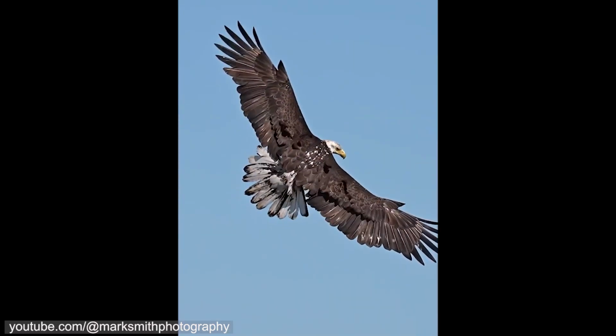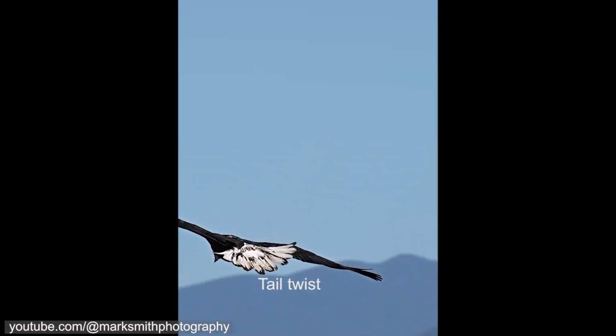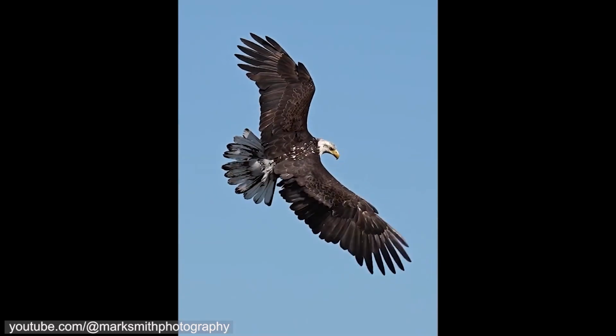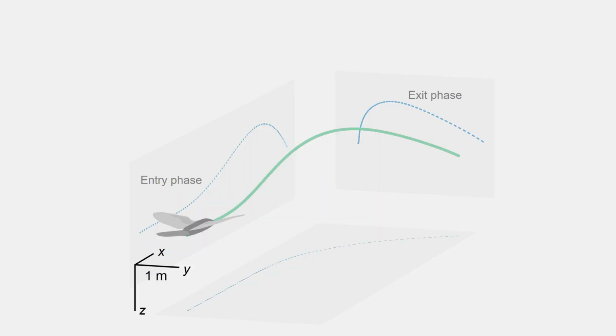We observed that birds also use tail twisting during high-speed sharp turns. In this maneuver, the bird coordinates tail twisting with a rapid pitch-up motion when entering the turn, and employs asymmetric wing morphing to effectively exit the turn. We reproduced the high-speed flight maneuver using the morphing drone.